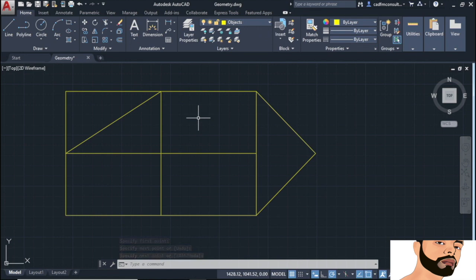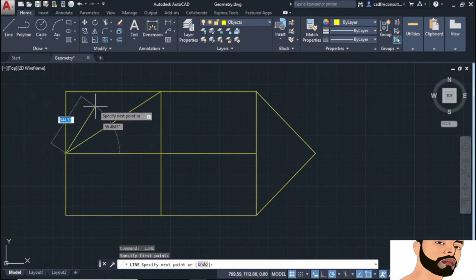You can also draw a line using coordinates. Let me show you what I mean. Go back to the line command, or you can press the space bar or enter to repeat the last command. So I'm going to use an object snap here. There's my endpoint there, and I left click. So my line is starting from that point. Now, what I can do is I can physically type in a coordinate here. And most coordinates, after you've placed a base point or a start point, are relative. So if I tell Autocad now that I want to go to a coordinate that is 350 along the x-axis and then 350 along the y-axis, that will take me to the right and upwards, providing those values are positive.